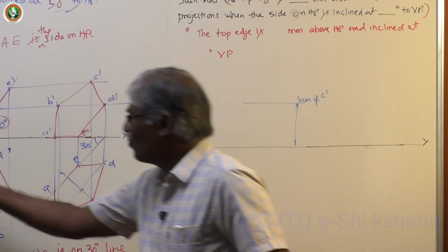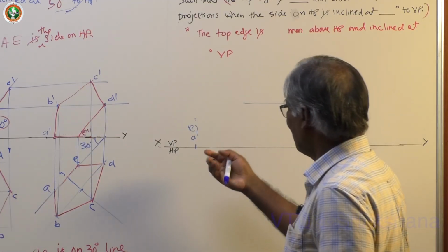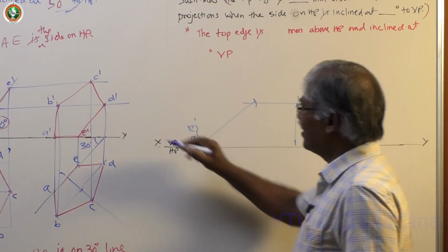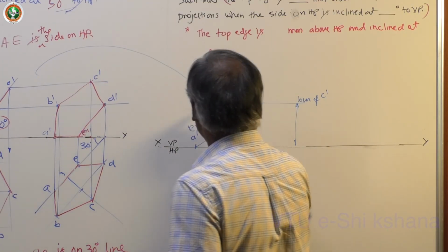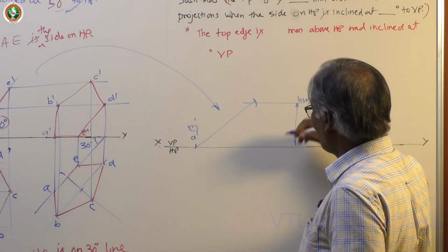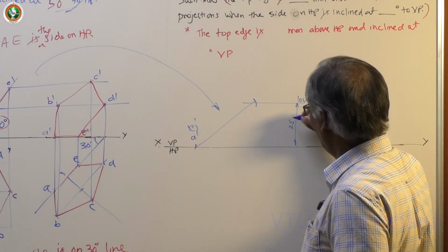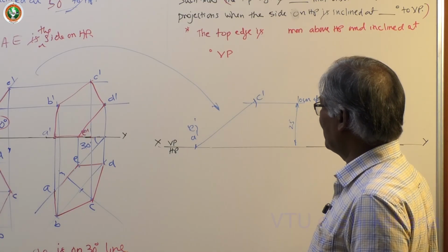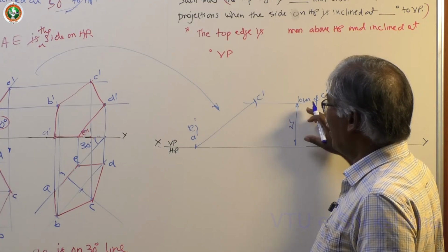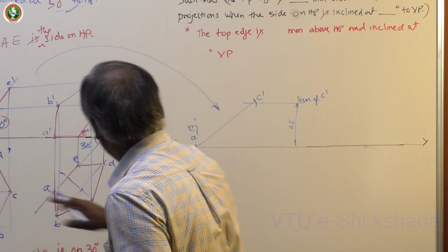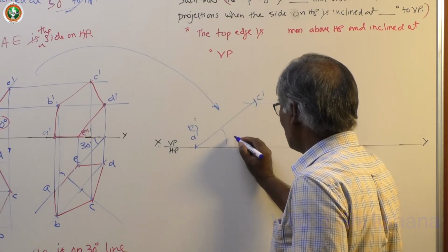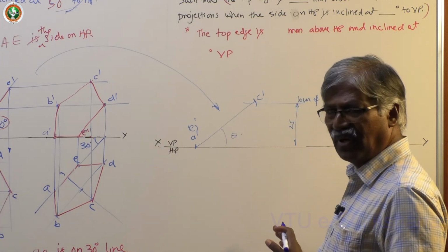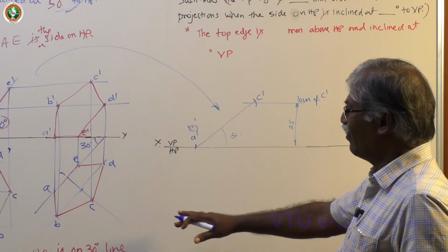What you do is, take the first figure, the front view, and draw an arc. See, this particular figure I am redrawing for this data. Suppose that this is 25 mm above HP. The top corner is 25 mm above HP. So take 25 mm, and with the front view length equal to the radius, draw an arc. Then this gets you the inclination theta. That's all. Next, the rest of the things are the same. You can go on working in the same fashion.